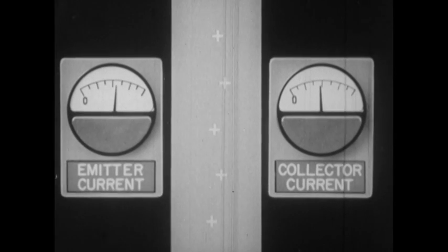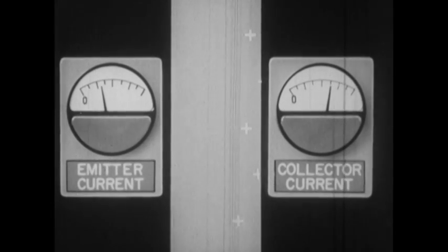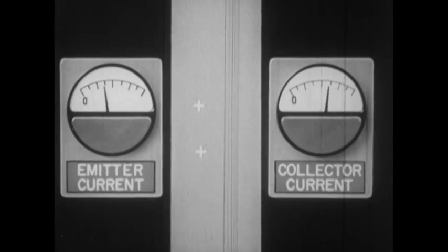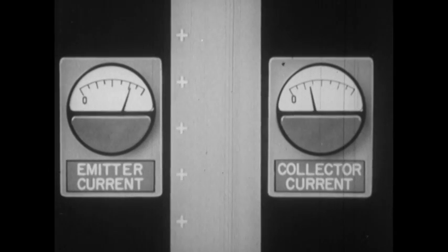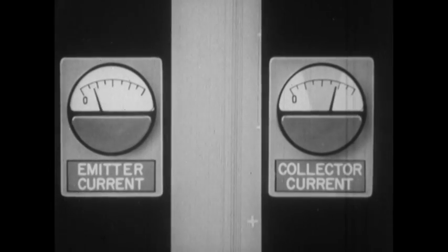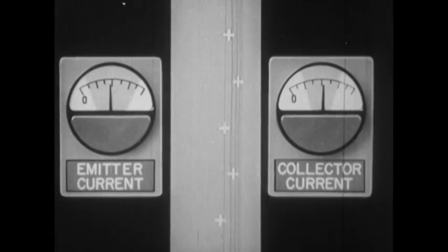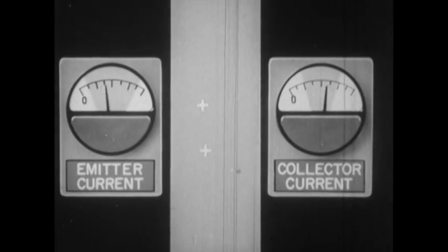By the time they arrive at the collector, they may be distributed over quite a bit of the base thickness. Since there are fewer holes where the peak should be, we have less peak current than we had at the emitter junction. Both current gain and power gain are reduced.